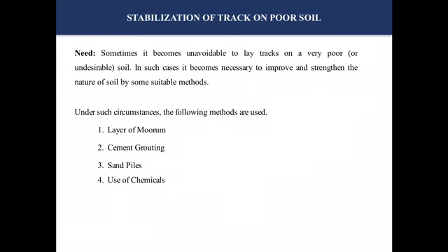In such cases, we have to remove that soil and borrow some good material so that the strength of the formation can be improved. But if you replace the entire poor soil, what will happen? The cost of construction will increase very much. The next option would be the stabilisation of the poor soil and making use of the locally available material.